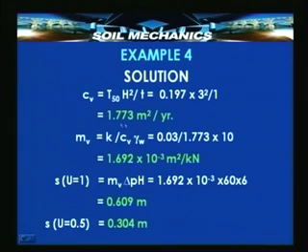The solution will be Cv is T50 h square by t, because we know the time corresponding to 50% consolidation. So, we need capital T50, which we know is 0.197. From this we get Cv. Obviously, once we know Cv, since we know K, we can calculate mv, and it is known that